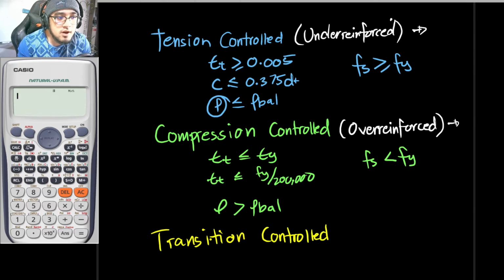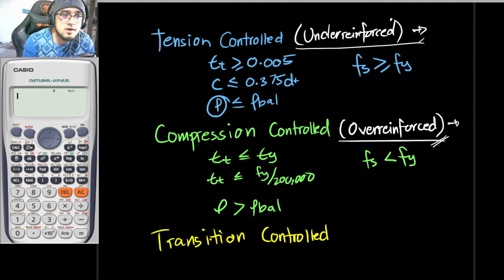In Tagalog, ang common misconception natin is that kapag sinabi nating over-reinforced, mas matibay yan kaysa under-reinforced. But the truth is, it is not. Because if your member is tension controlled, you are designing it in a way that if your member fails, the steel would be the one failing. And the failure of steel is a much more ductile failure. And pag ductile kasi, mas mabagal siya nag-fail.